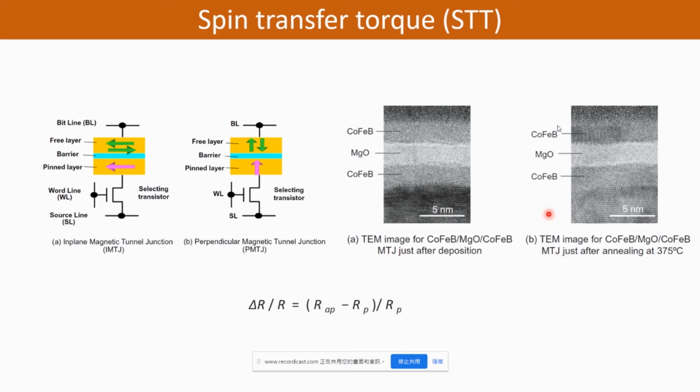And on the right side here is one example of increasing the TMR ratio. They use this sandwich structure, where the cobalt layer here was amorphous, and the MgO layer had a highly 001 oriented polycrystalline structure. We can see this in picture A on the left-hand side.